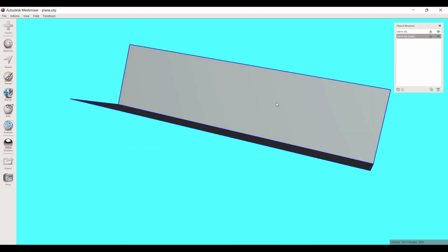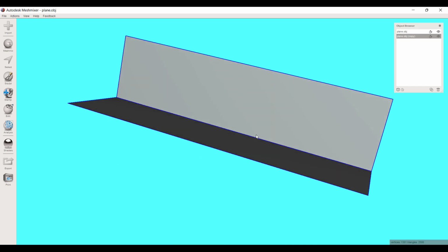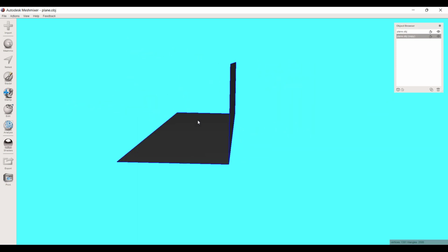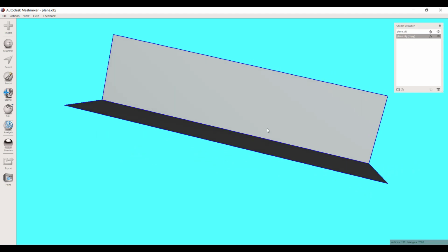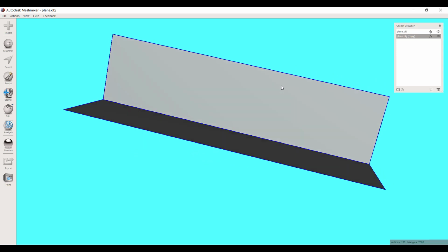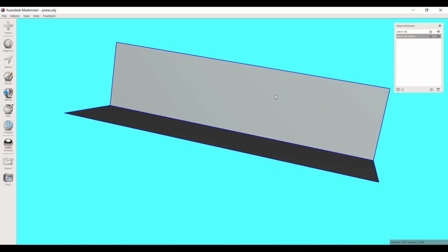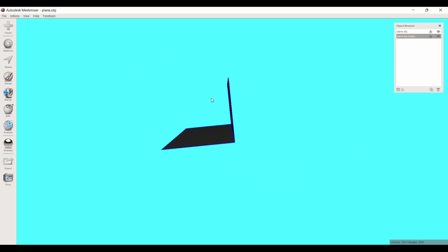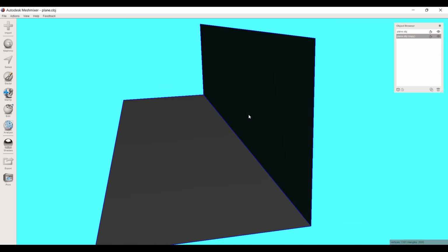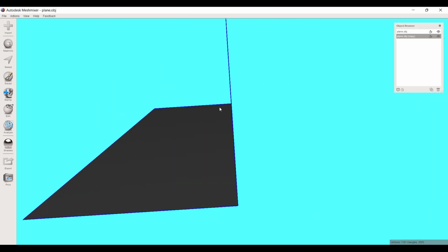So what was the thickness of the tank wall? It was 2.6 millimeters. Well, I want to give that a little bit of slop space, so I'm going to give it a thickness of about 3 millimeters. That's going to give it 2/10ths of a millimeter on each side, and that should be enough to let this thing fit relatively tight, but not be difficult to adjust or get seated. Okay, so how could I give this one-dimensional object a wall thickness of 3 millimeters?